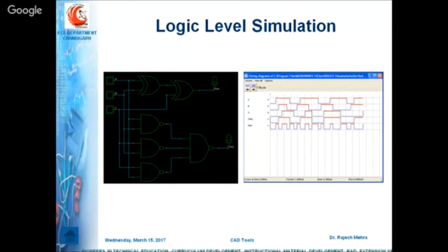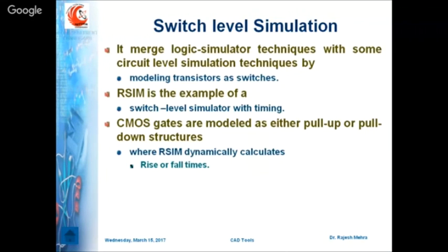We are creating the full adder at gate level, and here first of all you have to check the behavior of your circuit. So your software should be able to provide simulation at schematic level also. Only then you can check the logic or truth table of the full adder. So the right hand side is the simulation at schematic level. It should be there in your software, only then you can proceed further. Otherwise, without simulating it, without checking the behavior of your schematic, there is no point in moving ahead with your design. So first of all, you have to cross check the behavior of your design.